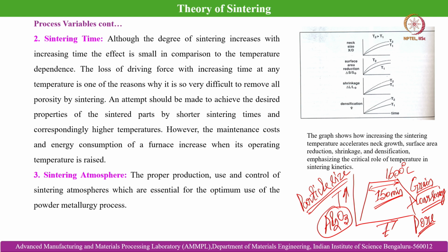Also, if we try to decrease the temperature to save on energy resources and then increase the sintering time, it becomes time inefficient, and that can cause production delays and losses. Hence we need to come up with an appropriate time-temperature combination for the particular material and also the particular part under development. Based on these requirements we need to optimize that.